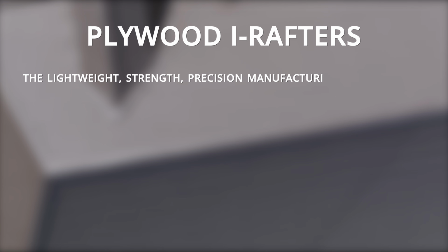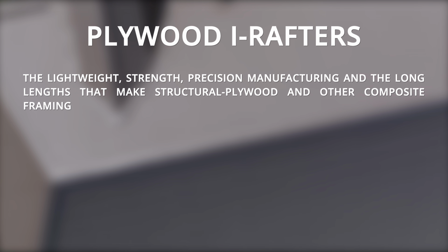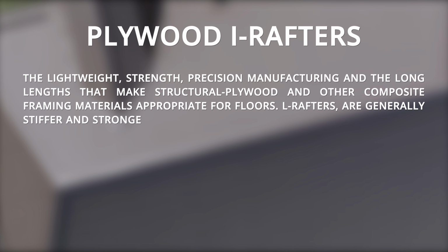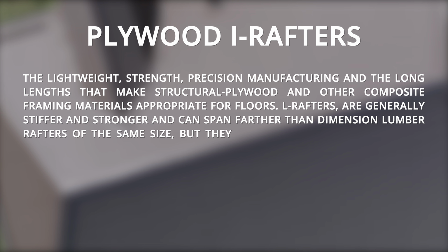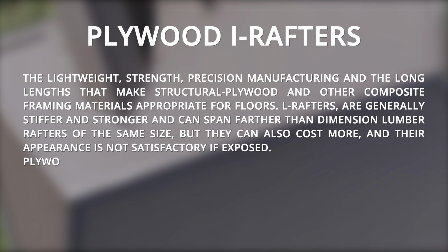Plywood I-RAFTERS. The lightweight, strength, precision manufacturing, and the long lengths that make structural plywood and other composite framing materials appropriate for floors. I-RAFTERS are generally stiffer and stronger and can span farther than dimensional lumber rafters of the same size. But they can also cost more, and their appearance is not satisfactory if exposed.